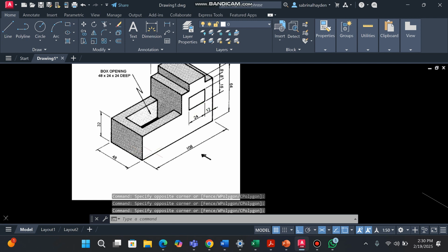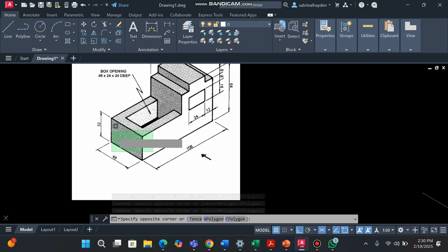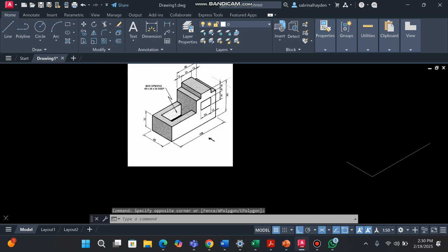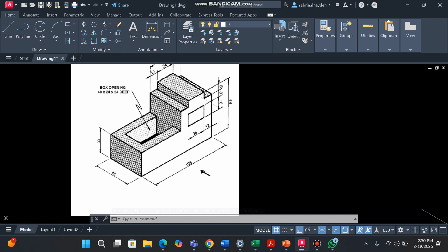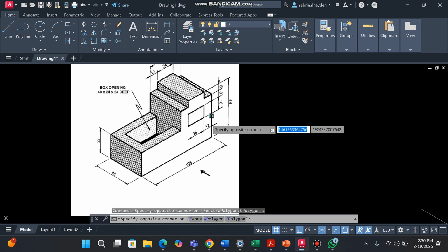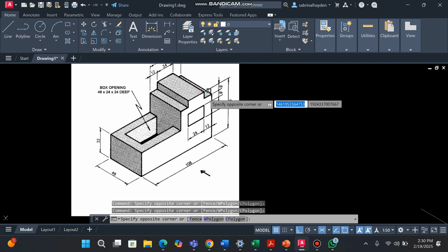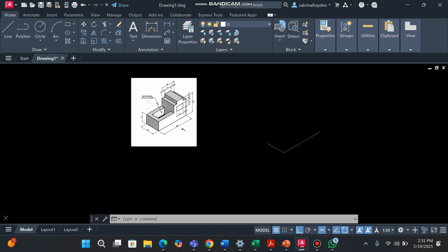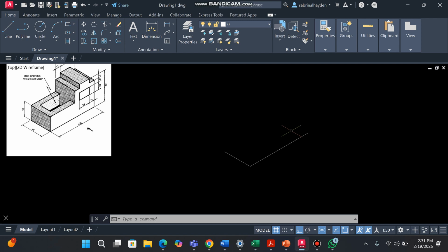Now, the drawing tells us that the measurements for the vertical lines that are off here, they're 32 millimeters. But over here, it doesn't tell us what this line is, because you can see 64. But 64 is not the measurement of this line right here, highlighted in green, right? This one right here that I'm trying to highlight. It's not 64. But we know that the little cutoff piece that is up here is 8 millimeters. So what we're going to do is minus 8 from 64. So that's going to leave us with 56 millimeters. Now when we complete our join at the top, we'll know if our measurement is correct.